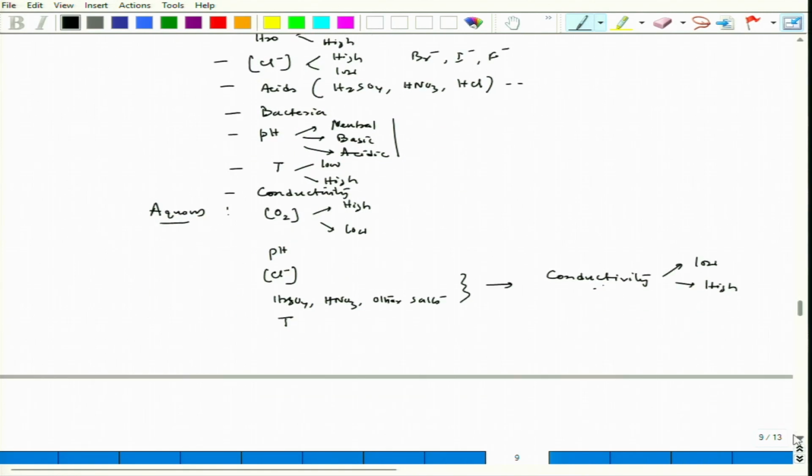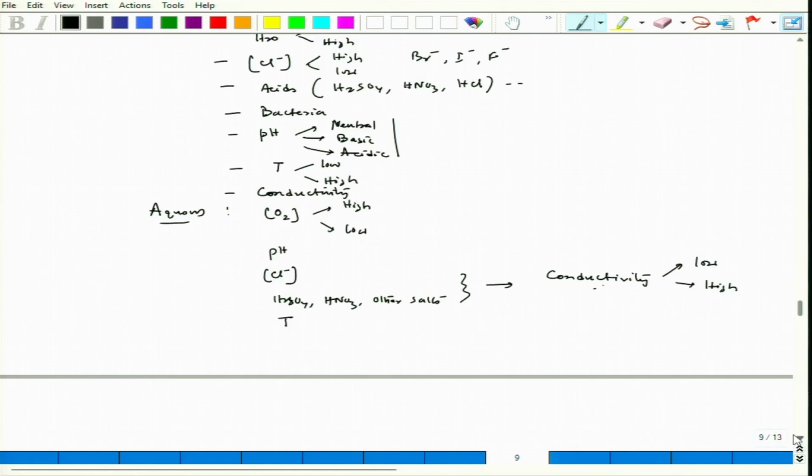Mainly high temperature always leads to problems in having passivity. So, if some material is protected because of the passive layer formation, if the temperature is very high, the passive layer can become destabilized. So, if you destabilize the passive layer, the corrosion would be much higher. Okay. So, temperature is a factor. Of course, here pressure means the partial pressure of oxygen.